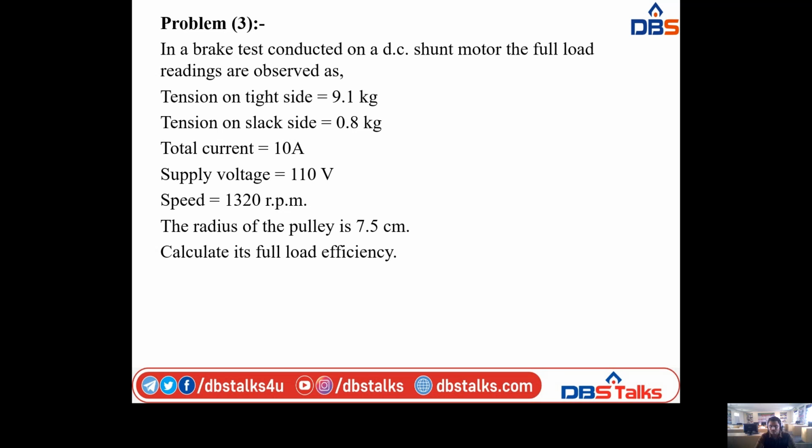So here we are considering the two machines, one is for the generator and one is for the motor. So the total losses formula is the input power minus output power. So here the input power is 8600 watts minus output power is 5120 watts, and finally we have the total losses in two machines is 3480 watts, and series field resistance for both the machines. You know the formula R is equal to V by I from the Ohm's law.